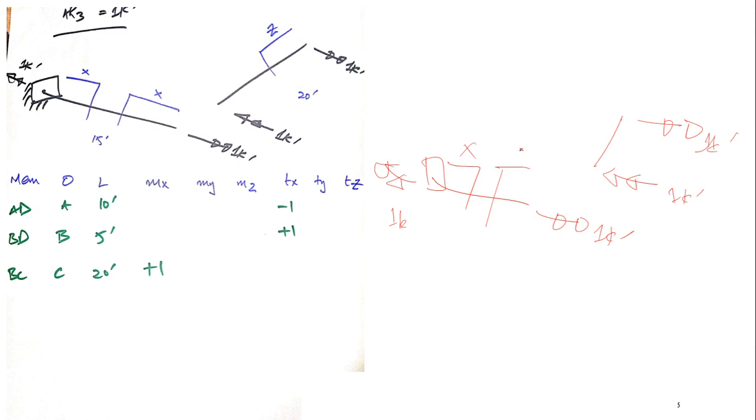So it all needs practice. This one is even simpler. You have applied this 1 kip-foot moment. This is your redundant action 3, so I'll balance it with an equal and opposite 1 kip-foot, and then balance here with 1 kip-foot, and again with 1 kip-foot. Sections are X and this is X, and sectioning is done like this. You should know that this is A, this is B, and this is C, and again this is B. For BC, your origin is C, so I have to find all moments here.